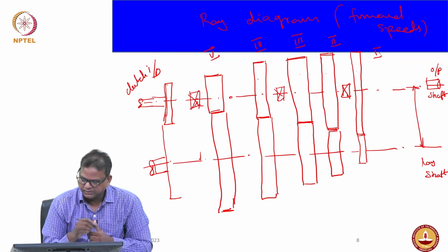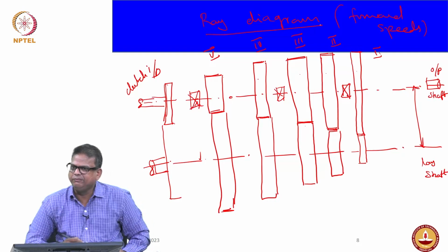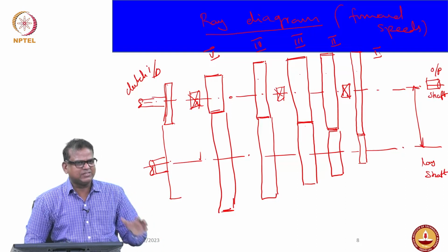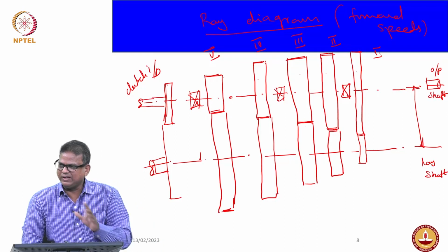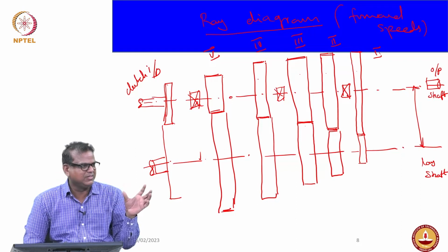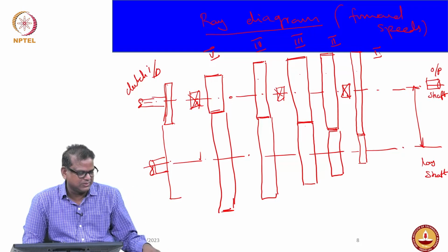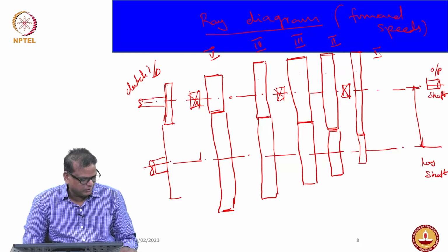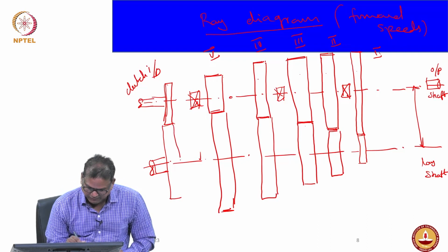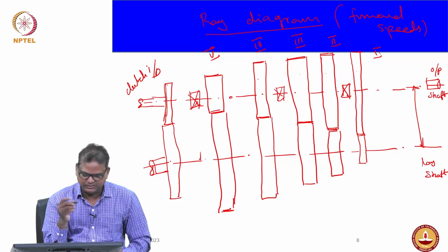So this is the ray diagram. This is the way the ray diagram needs to be arranged for the manual transmission. Much simpler, not as complex as a machine tool gearbox, because here you have 5 speeds. Generally it will go 7 or 8 plus 1 reverse. As we discussed, can we have the numbers also? We can have odd and even gear numbers.